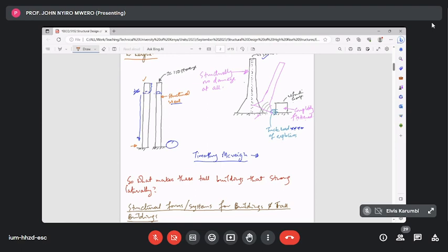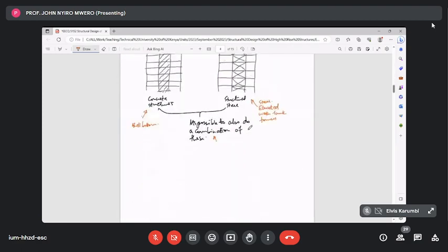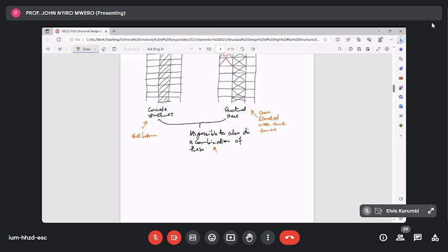During the investigations, the structural engineers asked themselves, if we had a concrete core in these buildings, would they have still collapsed in 30 minutes, 40 minutes? And the answer is a definitive no. Most probably they would have stayed for much longer, giving a lot more time for people to be evacuated, and a lot of lives would have been saved. So they changed their standards, I'm told. I've not read their standards, but I'm told they incorporated the need that if you're doing a tall building, definitely it will be out of structural steel, but you have to have a reinforced concrete core.